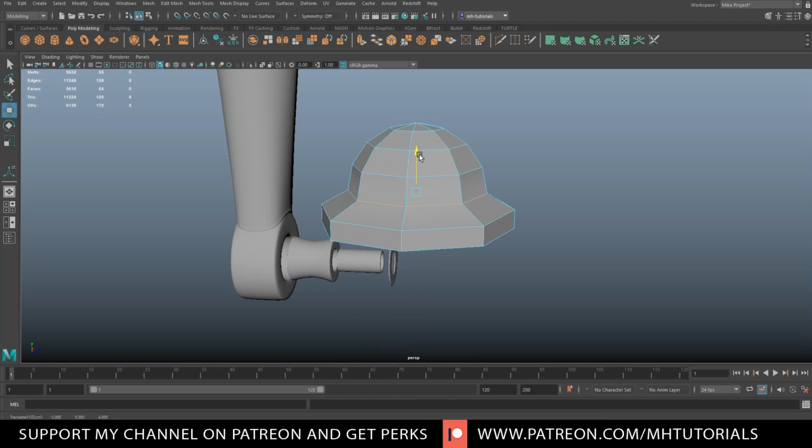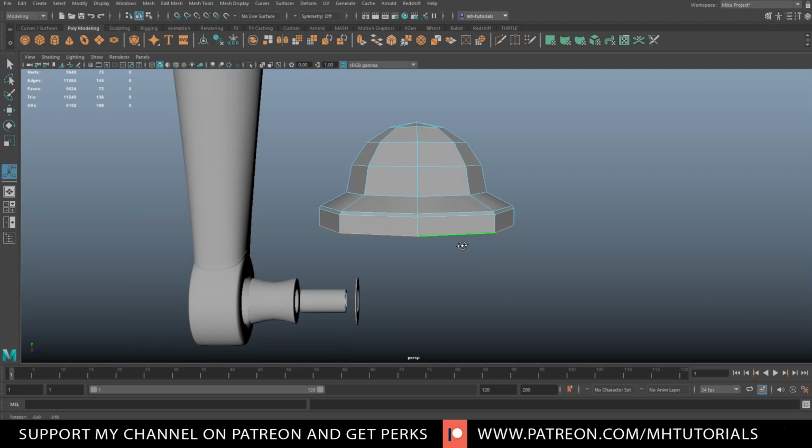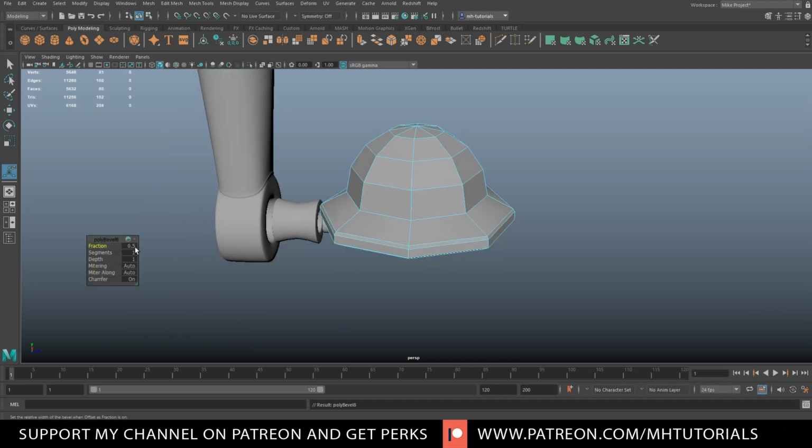Let's take this guy, push it down, not too far. We don't want to cut that in. Let's leave that alone. We'll take this guy, we'll bevel that, 0.1. And then let's see, we'll take this guy, and we need to bevel that as well, 0.1. And if we do a preview smooth, we might need to bevel this one as well, hit 3. Okay, yeah, we do. So we're going to go in here, we're going to go to edge, this guy, bevel that, 0.01.